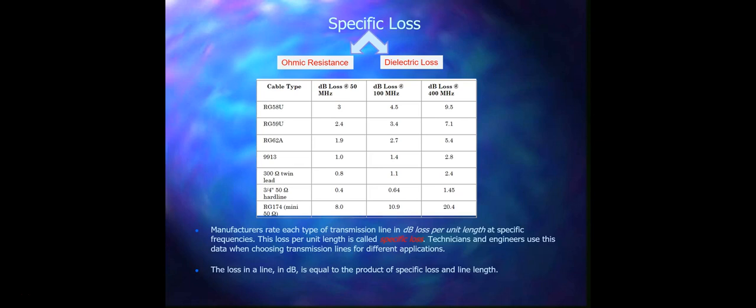And for the dielectric loss, the energy lost in the dielectric basically converts into heat, and we know that the best dielectric is air. The dielectric losses increase with frequency and are somewhat dependent on the voltage being applied, and they basically degrade the performance of the signal.